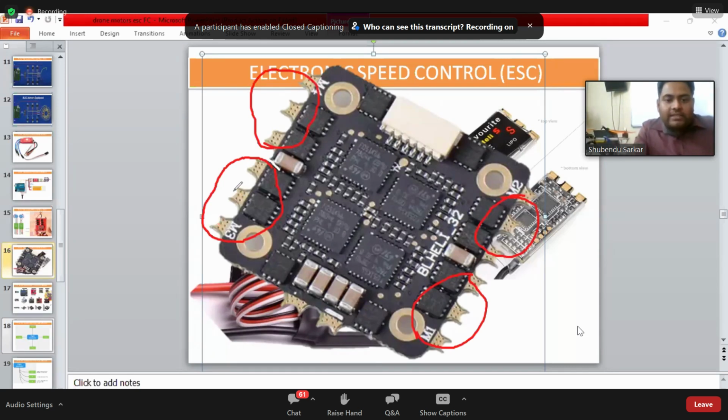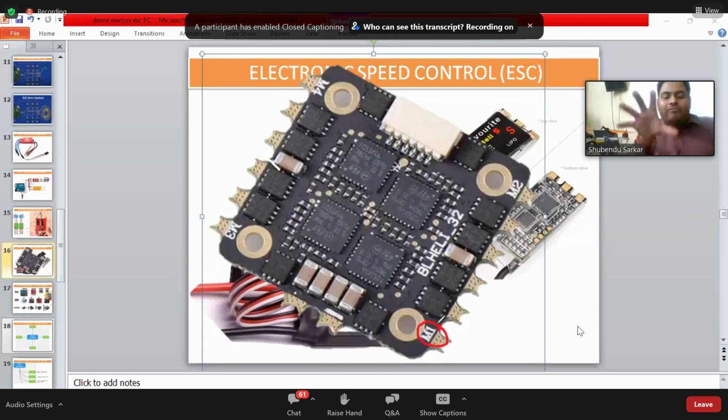So how can we decide where we need to start the connection? Now you see it's written over there, this is M1. M1 represents motor 1. Similarly, this represents motor 2. Over here it represents motor 3 and over here it represents motor 4. You have to follow that mark so that you can connect the right motor with the right connection. But now someone is going to ask, is it necessary to follow these marks? Why don't we just connect the ESCs, because we are going to connect the wires properly? Is it necessary to follow the mark?